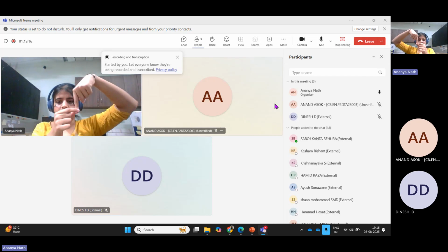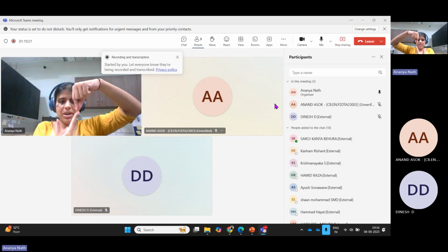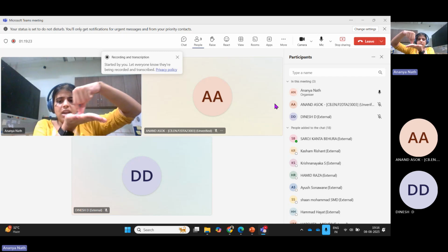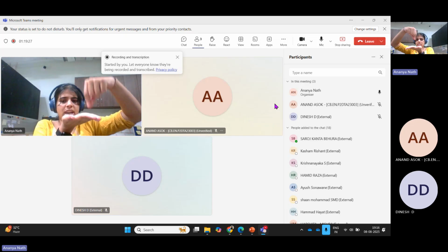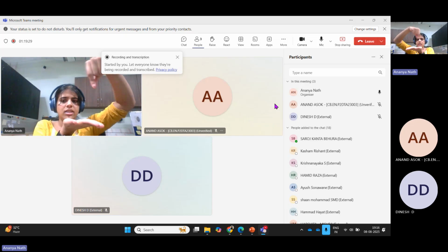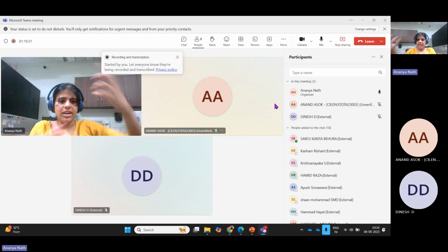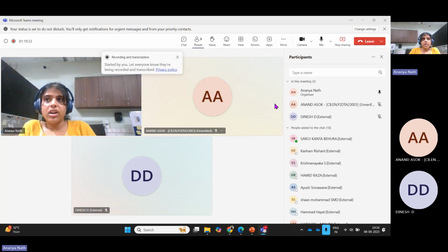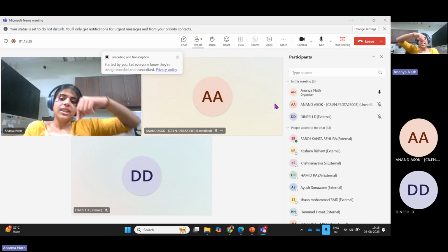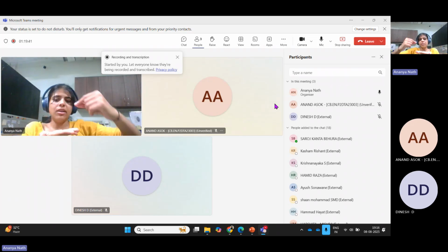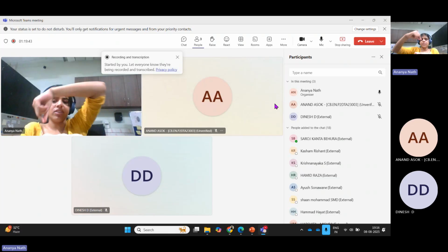Generally, this finger is my tool from which the material is coming, and this is my build plate. Normally, the printing will take place like this: one layer, second layer, third layer, fourth layer. But if your tool is mounted on a robotic arm which has more degrees of freedom, then even your layer may look like this 3D surface.